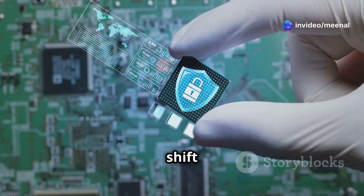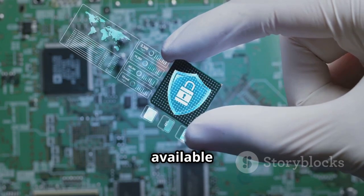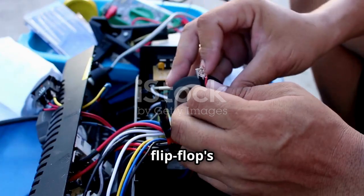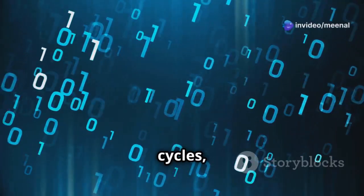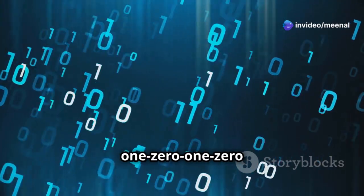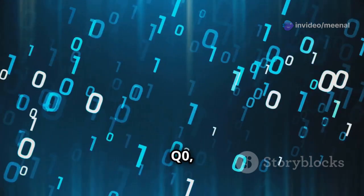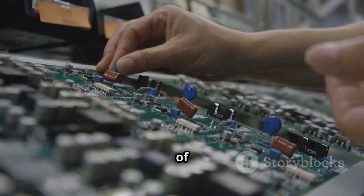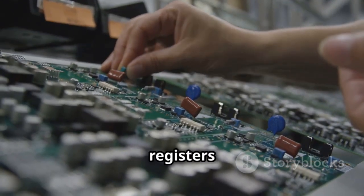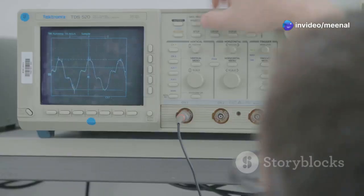In a SIPO shift register, data enters serially, but the outputs are available in parallel. Each flip-flop's output is connected to a separate output line. After 4 clock cycles, the input data, 1010, is available simultaneously at the parallel outputs Q0, Q1, Q2, and Q3. This parallel availability of data makes SIPO shift registers suitable for applications like serial to parallel data conversion.